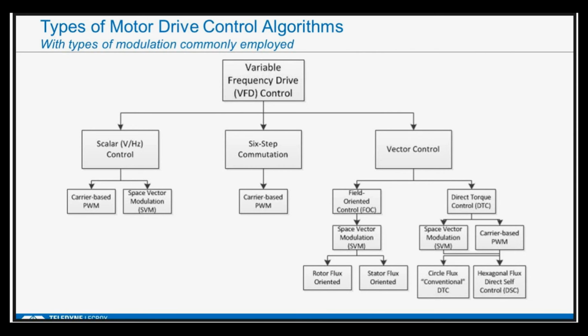The vector control, you could really break that down into lots of different other categories. Typically, it's a rotor flux-oriented control system. Larger AC induction motors might use a direct torque control, which is really very different from a field-oriented control. It tries to achieve a more simplified approach, but it's using that same kind of space vector modulation technique to control the gate drivers.